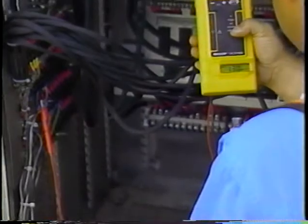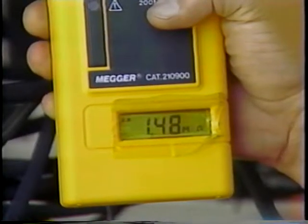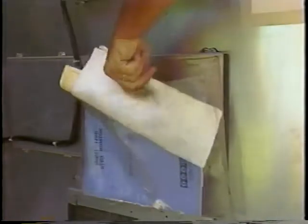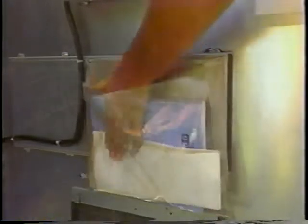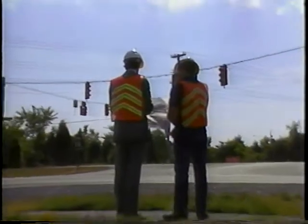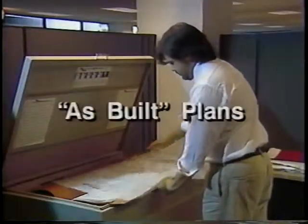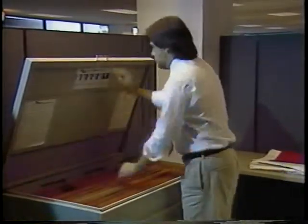After all the loops and cables have been installed, it is time to conduct the tests again. The results of these tests should be recorded on the installation data sheet. Also, any modification made to the original plan drawings should be noted and dated. The exact readings from the tests and the modified plans should be verified by an inspector. Finally, these as-built plans should be stored for future maintenance or repair work.